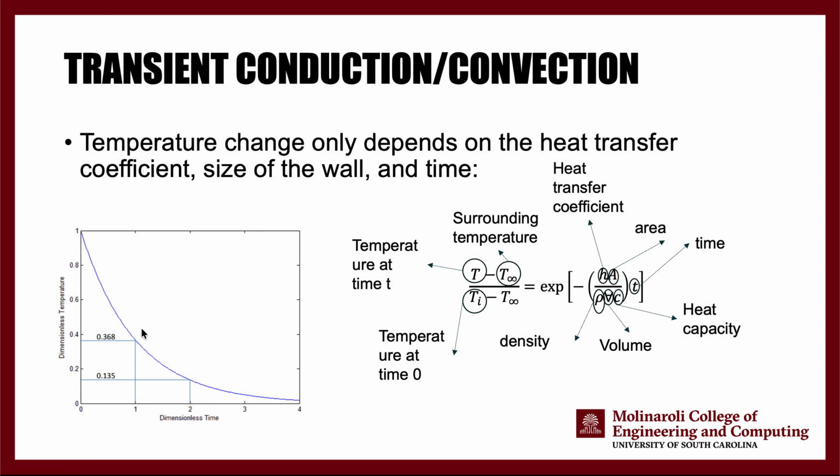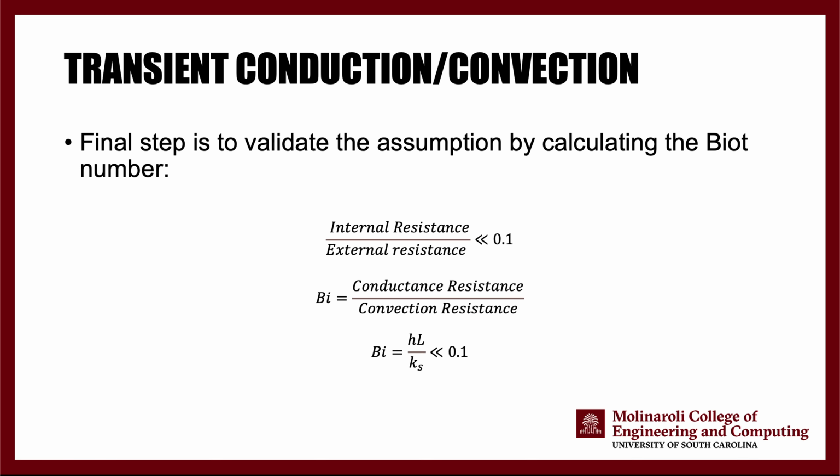And then you just essentially take 2 of these points, put it in this equation to find heat transfer coefficient. And the idea is you can take as many 2 points as you want on this graph, meaning that you can have more than one heat transfer coefficient calculations, meaning that you can and must do a statistical analysis.